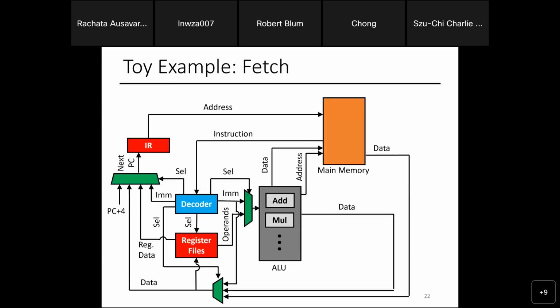Now here's the visualization of the same thing I drew earlier. The blue thing is the decoder. In that design, I took the instruction in, and based on the 16-bit instruction that you see, it sends out the control signals. So let's say I want to do an add. This becomes the program counter's address. And let's say you see the add R0, R1, and R2 here. Basically, this means I want to do R1 plus R2 and write the result to R0. With me so far? So that's the instruction I'm pointing to.